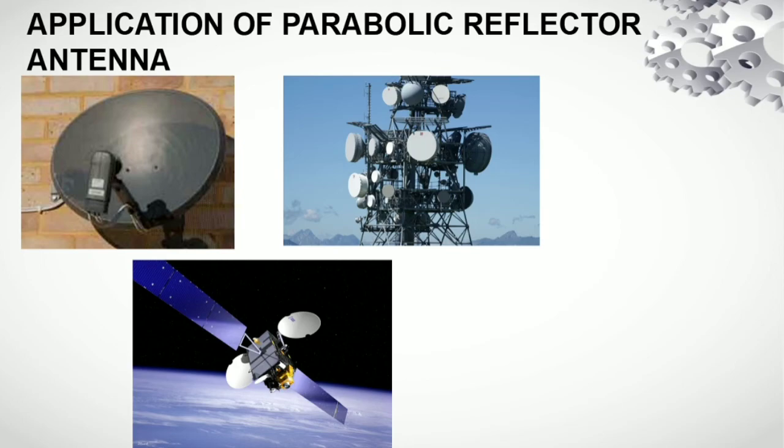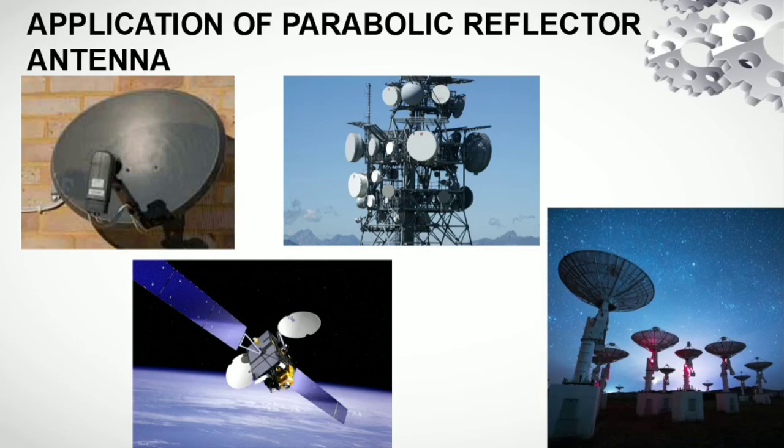And lastly, the last application of the parabolic antenna is radio astronomy. Radio astronomy is an area where very high levels of gain and directivity are required. Accordingly, the parabolic reflector antenna is an ideal choice. In all these applications, very high levels of gain are required to receive the incoming signals that are often at a very low level. For transmitting, this type of RF antenna design is able to concentrate the available radiated power into a narrow beam width, ensuring all the available power is radiated in the required direction.